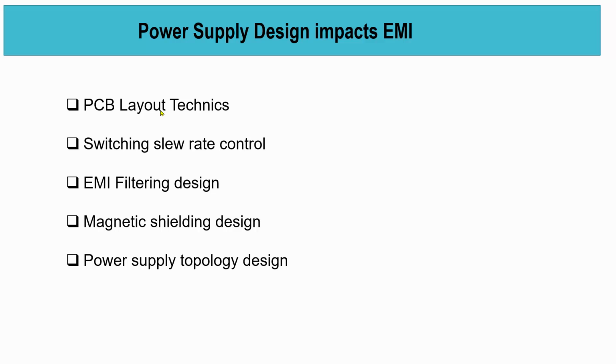The switching of your FET, your diode, the slew rate, how fast it is, could generate EMI noise back to the source. Your EMI filtering design is the most important one too. Also magnetic shielding design. And your power supply topology could also impact your EMI.